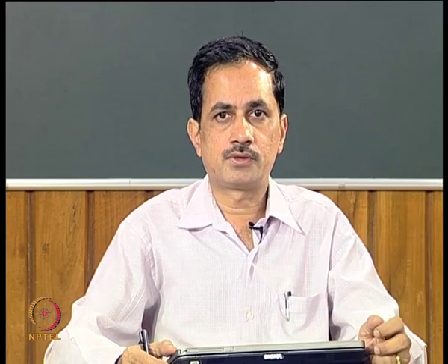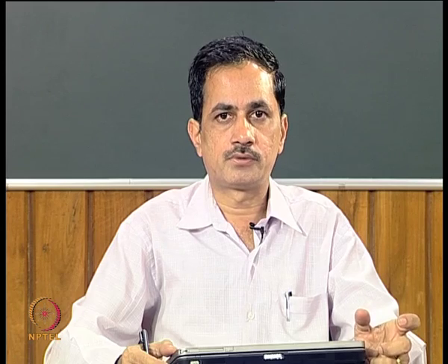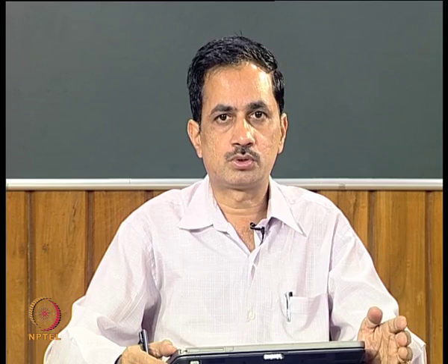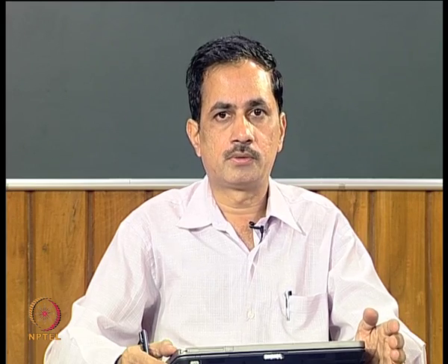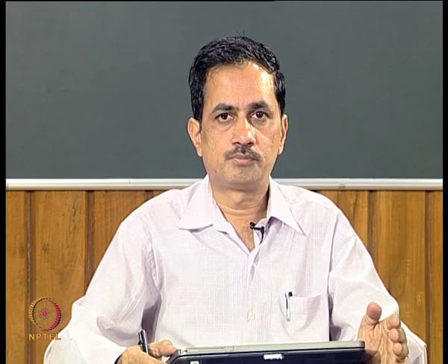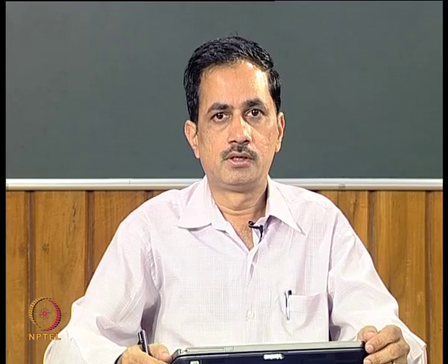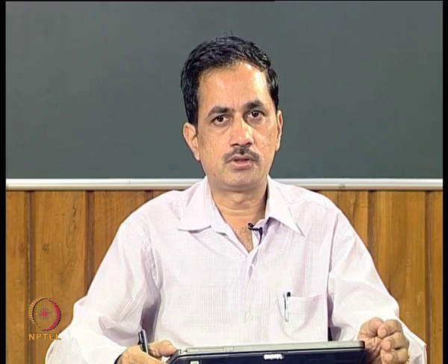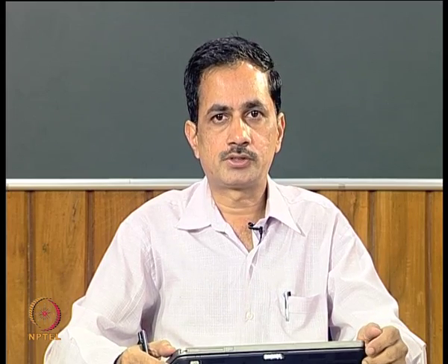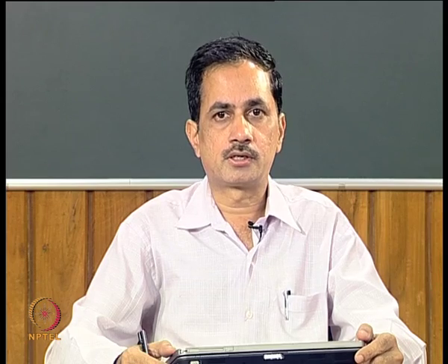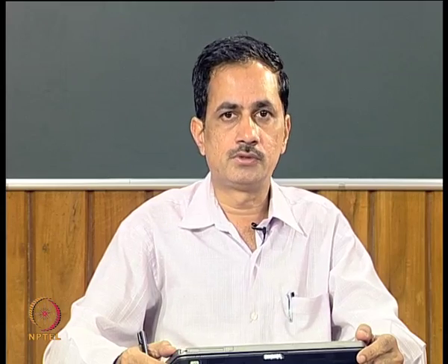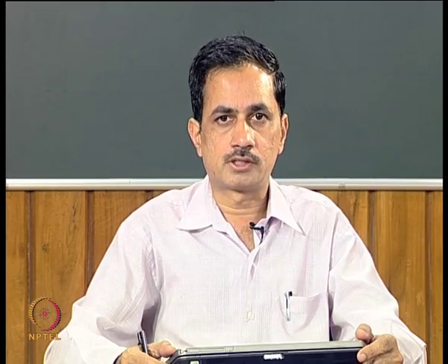With a very simple case of a simply supported rotor, we tried to show the analysis of how this modal balancing can be used to balance the rotor up to the second mode by using two planes, which will balance not only the first mode but also the second mode. In the subsequent lecture, we will be taking up another method which is more advanced and more powerful. That is the influence coefficient method for flexible rotor balancing.